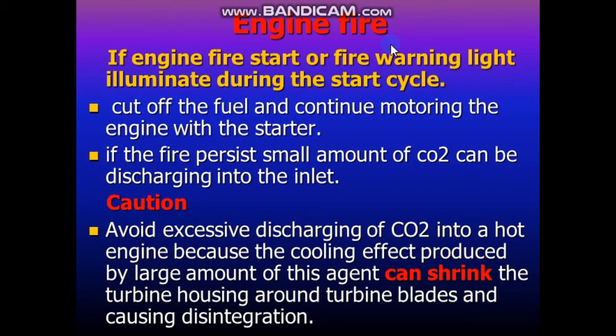What does that mean? It means that when a lot of CO2 goes into the turbine housing, it will cool the turbine, and this cold will make the housing shrink, and when it shrinks it will affect our turbine blades. When the turbine is affected, it will cause misalignment or crashing together between the housing and the turbine blade.